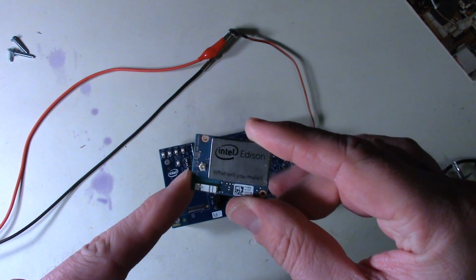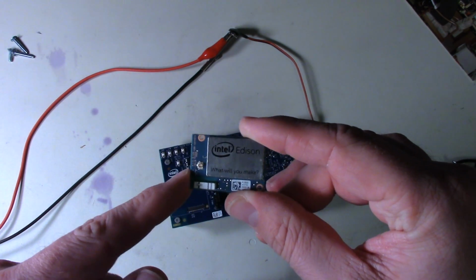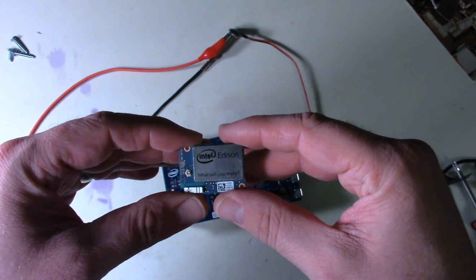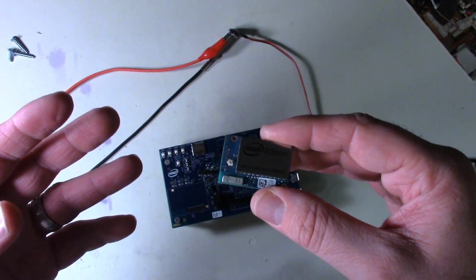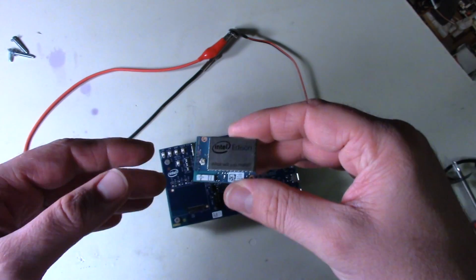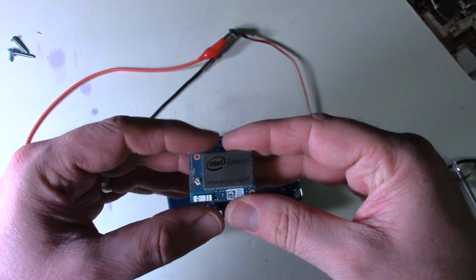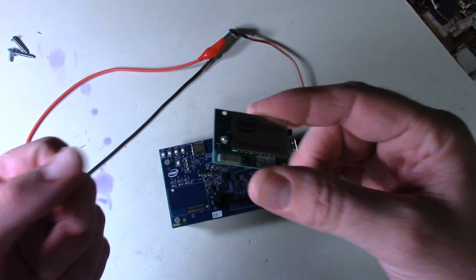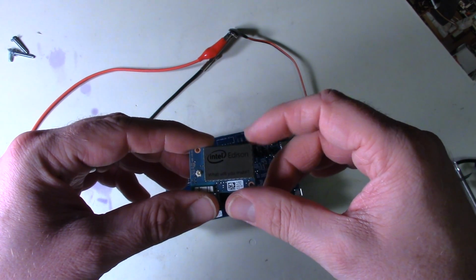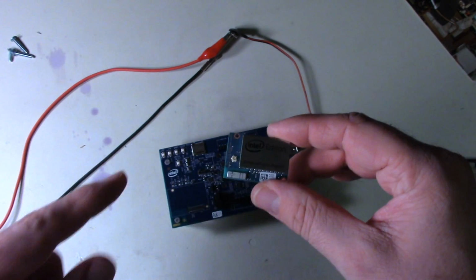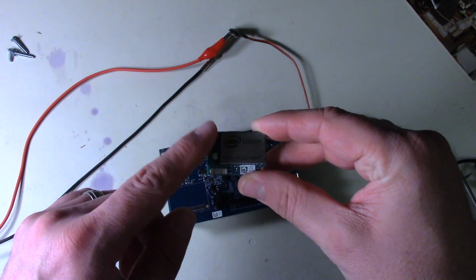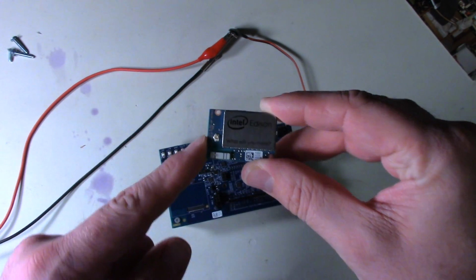It may cause it to heat excessively, because I'm sure they probably put protective circuitry in there. So there's probably maybe a little Zener diode or something that will clamp it. If you leave it on there for a while, it's going to get hot, because it's trying to clamp that down. So it's not good to run it at 5 volts. I think 4.8 or something. Don't quote me on that, but I believe 4.8 is the highest you want to go. Otherwise, you're going to cause damage to the chip if you power it directly.